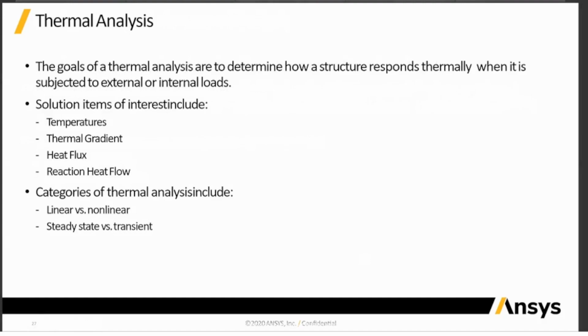Then there is a thermal analysis which can also be done. If you want to see the thermal effects, then we can do the thermal analysis. The solution items of interest may include the temperatures, thermal gradients, heat flux, reaction heat flow, etc. Thermal analysis includes linear versus non-linear thermal analysis, and also steady state versus transient thermal analysis.